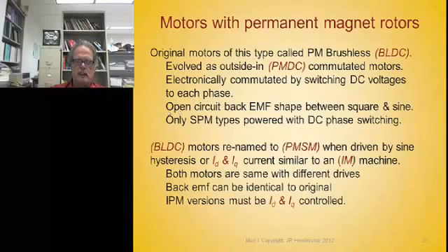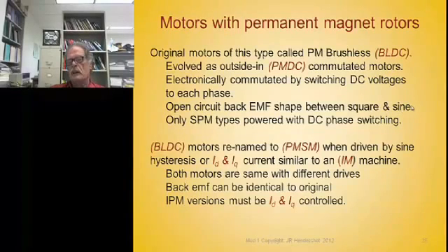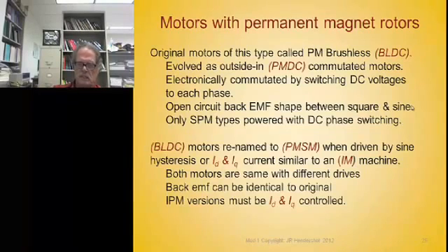If you take these motors and you spin them like a generator, you drive them. Take a motor and stick a shaft in a drill press and spin it with the drill press, and look at the voltage across the lead wires, and put that output on a scope and see its shape. You can see its amplitude, frequency, and its shape on an oscilloscope.